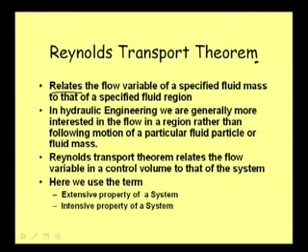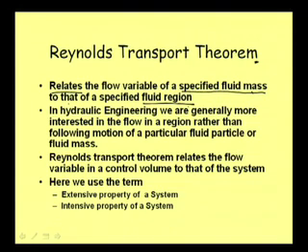That means, suppose we know the flow variable of a specified fluid mass, then we can relate this property to that of a specified fluid region. By fluid region we mean, say, a control volume. If we know the property of the fluid mass, then we can relate that to the property of the entire fluid region. This is what the Reynolds transport theorem does.